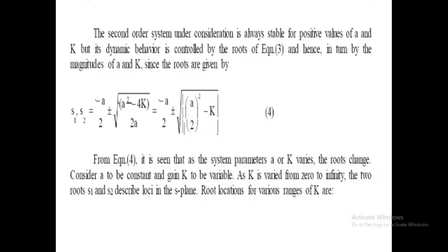The root locus is symmetrical about the real axis, and the roots of the characteristic equation are either real or complex conjugate, or a combination of both. Therefore, their locus must be symmetrical about the real axis.